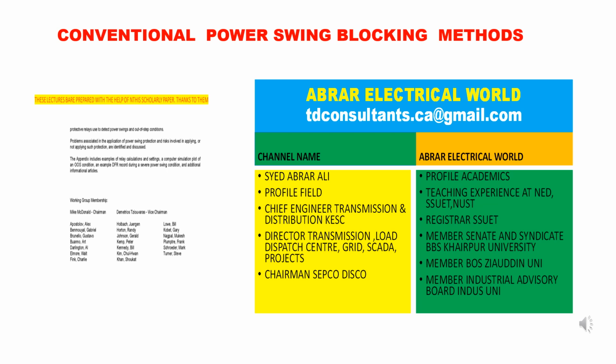It results in the inadvertent, unwanted mal-operation of the relays. Distance relays operate because they see power swing as a fault at that point, because they measure the voltage and current. So there are various methods which are in use in the power system, and I have mentioned them in my other lectures in the classroom.